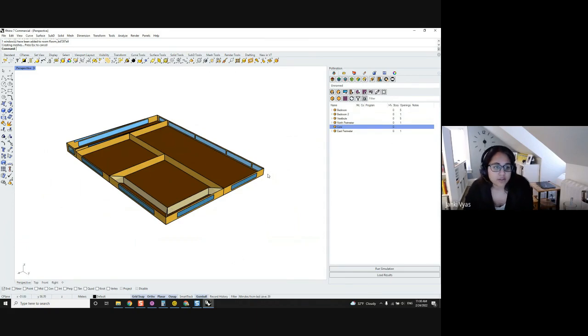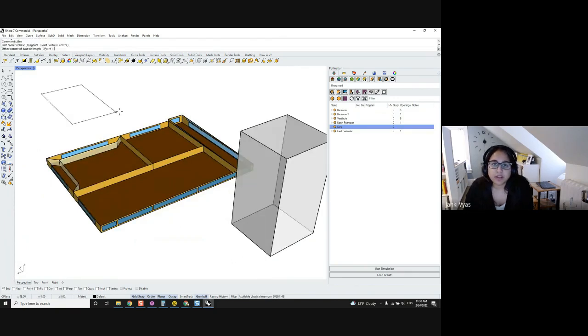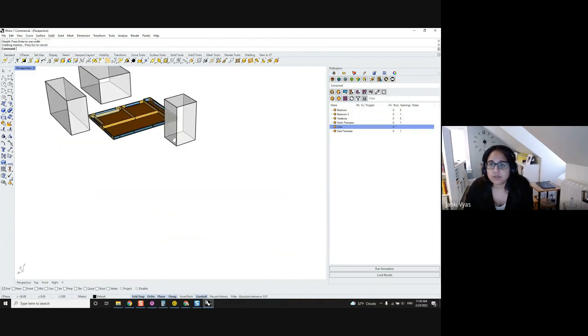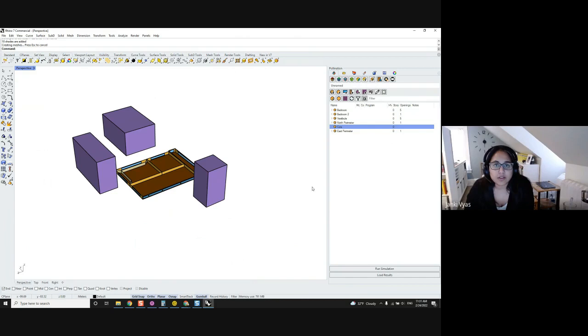We're almost ready to start simulating. We want to add some context. To add context, we're assuming most people will have a context that's coming from some kind of outdoor tool. So our workflow to add shades or context is to go to add shades, select site context and shades, and use the geometry that's drawn in Rhino. I just used the rectangle command to create some buildings as site geometry and added them as context. So we have context added.